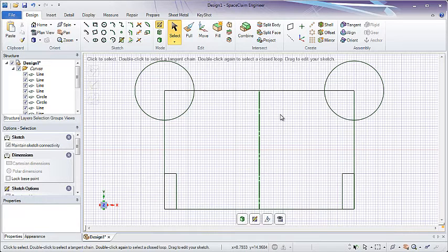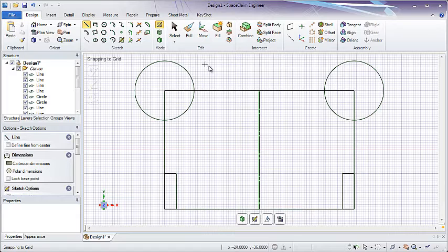What this means now is that anything I create on one side of the model will be created on the other side. Notice two quick sketches makes this on one side and makes this on the other side. To remove these, I'm simply going to undo by going to the Quick Access toolbar and pressing undo.